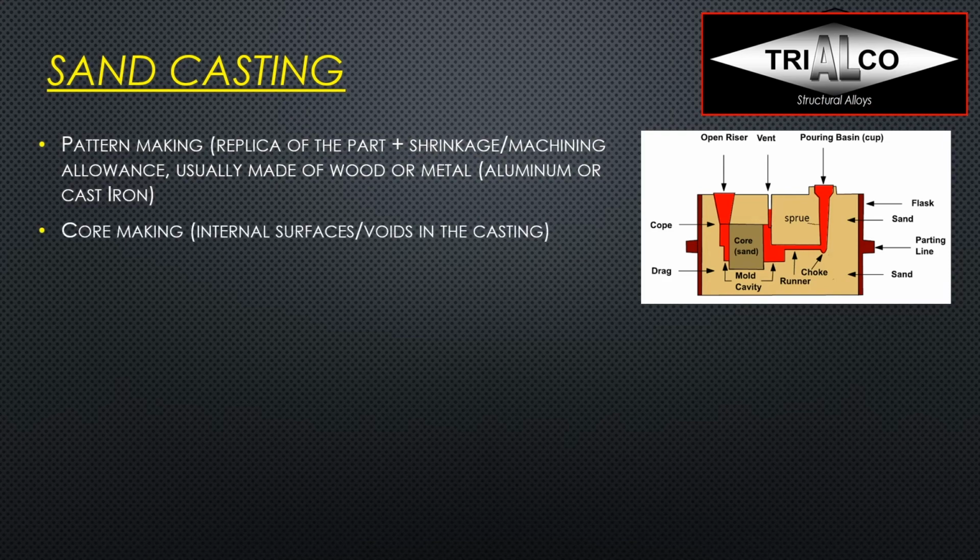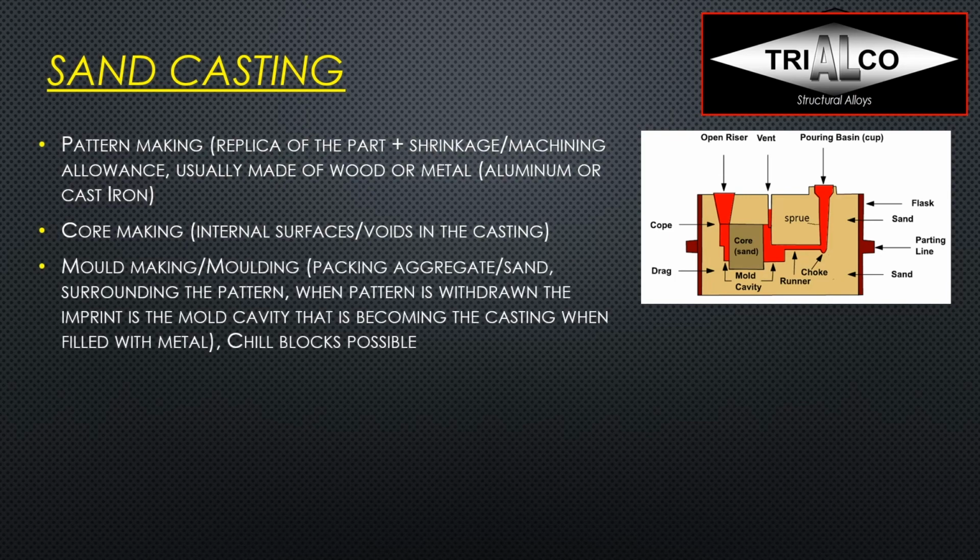and then the mold making. The packing aggregate and sand is surrounding the pattern now. It's compacted, and when the pattern is withdrawn, the imprint is the mold cavity itself. So that's going to become the casting when it's filled with metal.